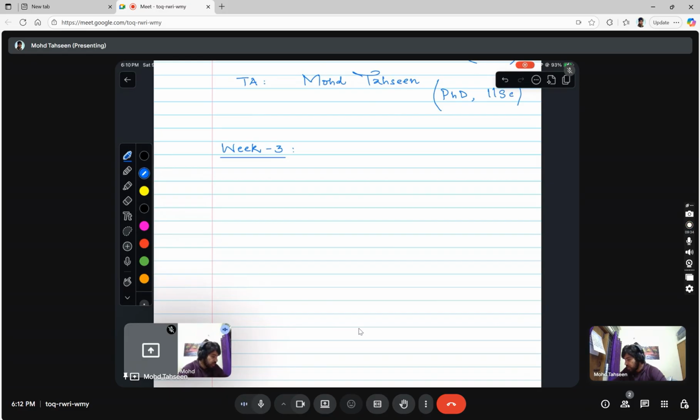And then we looked at how the measured data can be fitted onto a simple model, let's say a resistor in parallel with a capacitance. We looked at how we can fit the experimental data onto these models, and how we can determine the properties of a sample based on this data.